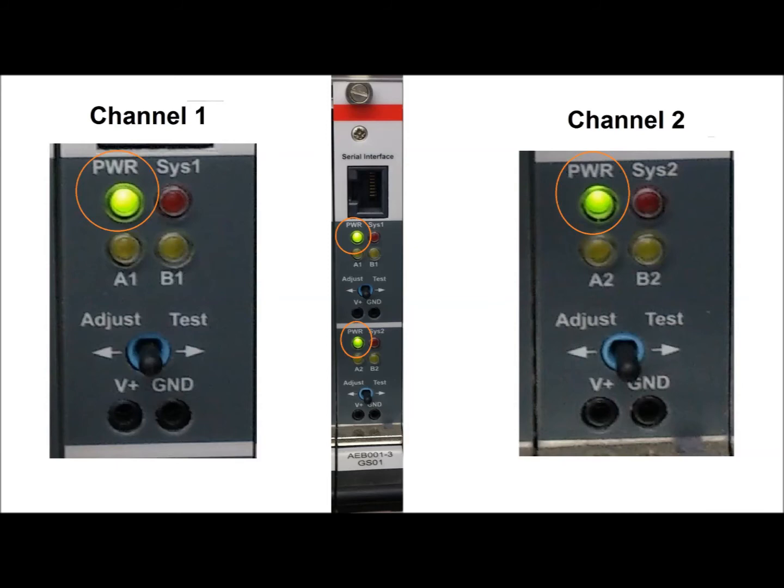The System 1 and System 2 LEDs are red and they indicate the occupational dampening state of the wheel sensors of the RSR 123. If a wheel sensor system is not currently dampened, the LED will not be lit. If a wheel sensor system is dampened, the LED for the wheel sensor system will be lit steady. If a wheel sensor system exhibits a fault, the LED for the wheel sensor system will flash.